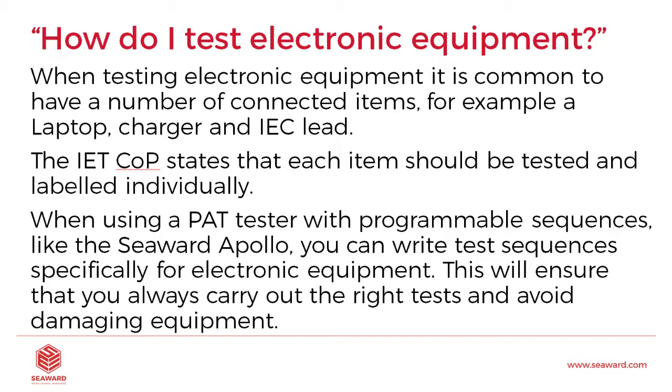So also, when testing electronic equipment, it is common to have a number of connected items. For example, your laptops, chargers, IEC kettle leads, that sort of thing. So the IET Code of Practice states that each item should be tested and labelled individually. Again, it's very common if you've got your normal IEC kettle lead plugged into the back of your PC, people will treat it as one item. But with the cable being detachable, they should all be tested separately as the PC and as the lead, and obviously labelled appropriately for each item.